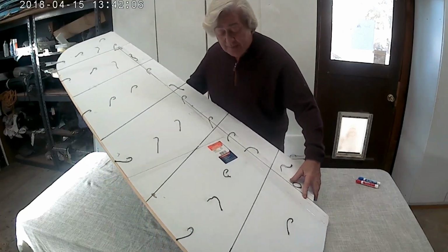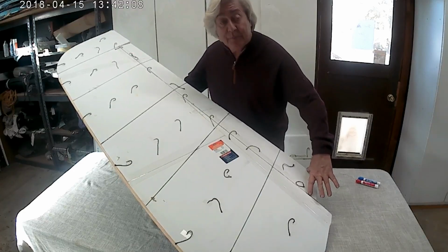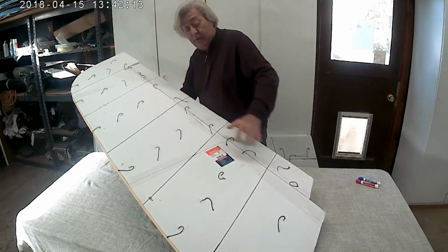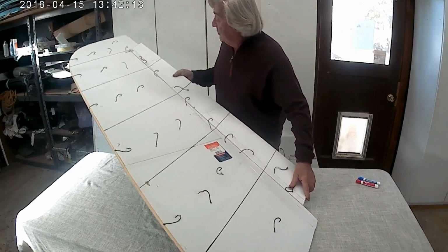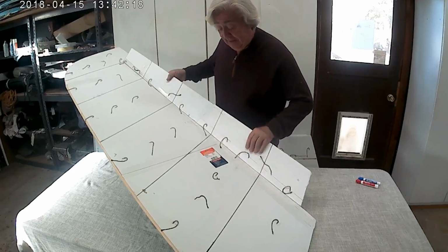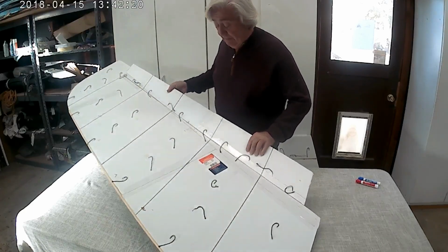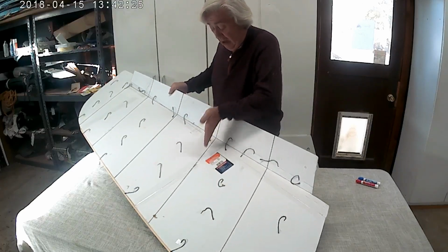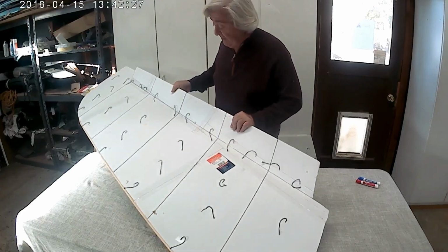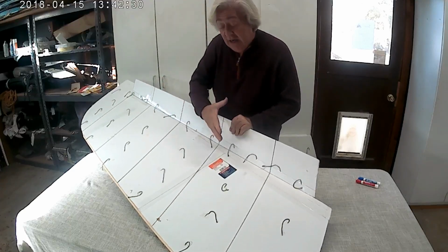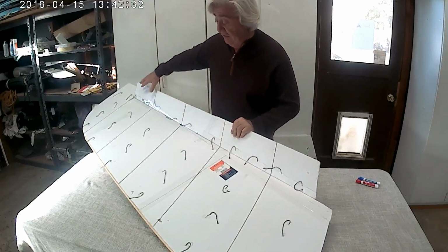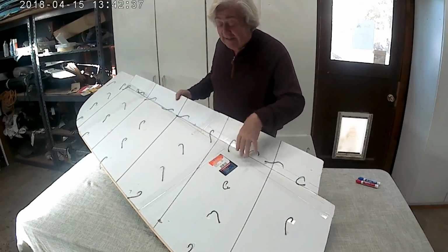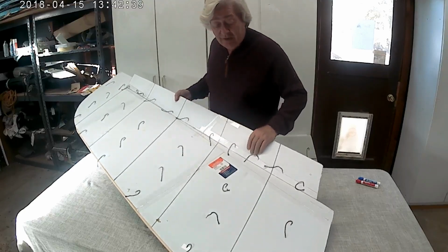Because the wing is tapered, this elevon, being a set percentage of chord, is wider at the root than it is at the tip. So, when you deflect it up like this, you're presenting to the relative wind coming in a wall, a fence of sorts, and because it's tapered this way, you're just encouraging the wind to go this way. It's easier, and I'm going to explain in a minute why it's easier for the air to just turn and go out along the elevon.